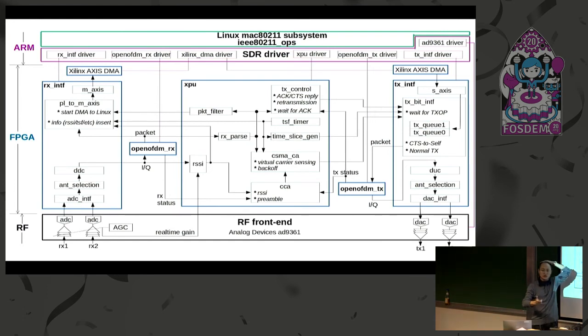You should do a packet filter, otherwise the workload of Linux is too much. Here we also need to handle all the DMA stuff, RX DMA. From FPGA to Linux, we set up a ring buffer DMA that keeps running in the background. In the driver, we check the DMA status. That's how we know the latest packet.